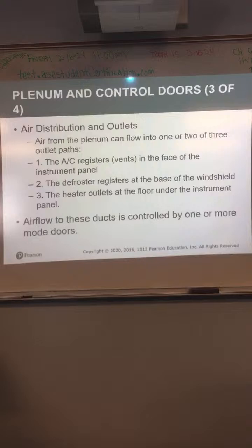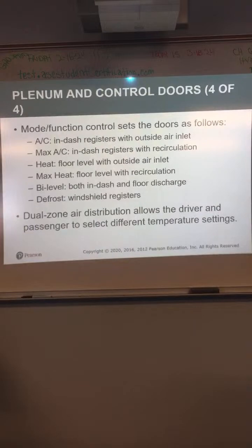Air distribution outlets. Air from the plenum flows to one or two or three of the outlet paths. Your registers, meaning your vents that blow right in your face. The defrost blows at the base of the windshield, heater at the floor. Airflow to these ducts is controlled by one or more mode doors. Mode means where do you want it to come out, okay?